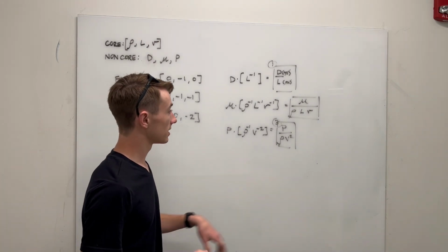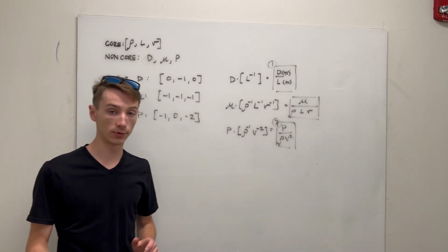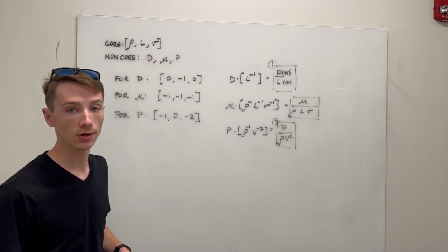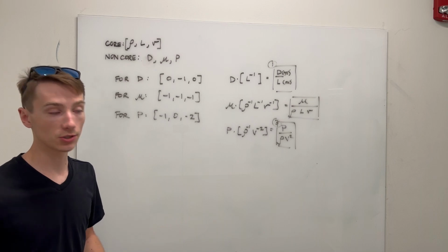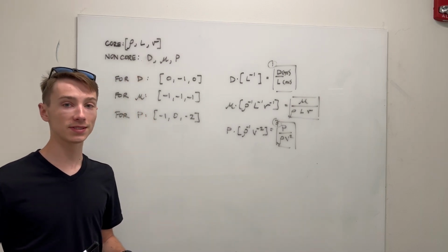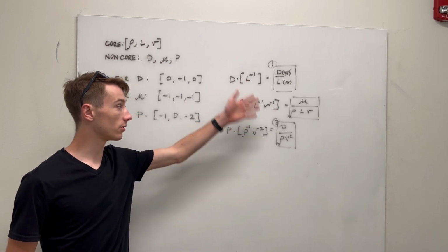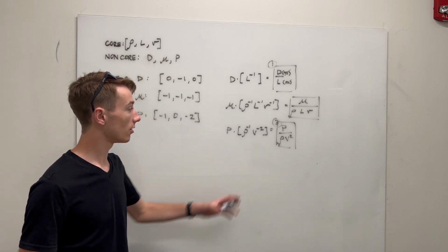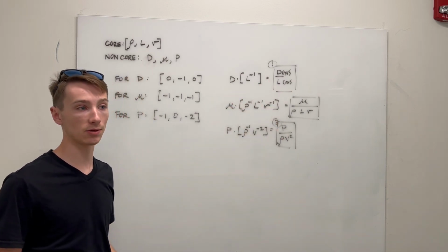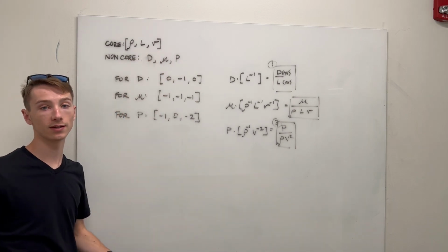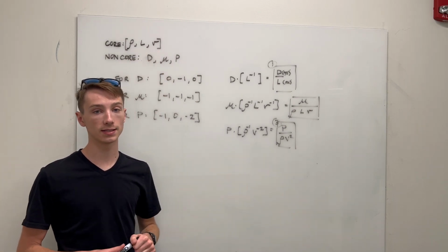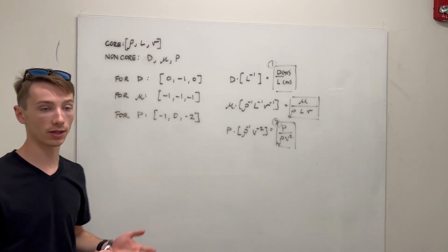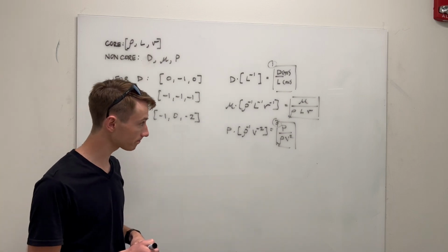You'll notice that this one is eerily close to what we call the Reynolds number. The Reynolds number is also a dimensionless group. So if I said we can only have 3 unique dimensionless groups out of this, how can there be another one? Well, the Reynolds number isn't actually unique from these 3. These 3 are unique to each other, but there are other dimensionless groups that we can make. There are a lot of them, in fact. But they're all just combinations of these 3, and the Reynolds number happens to be one of them with this set of core variables. If you switch your set of core variables and your non-core variables, you will get different dimensionless groups, but they will all be multiples of the 3 that you come up with. Every existing one.